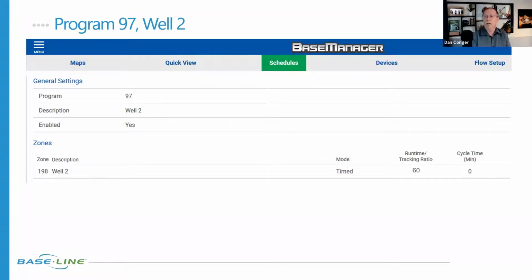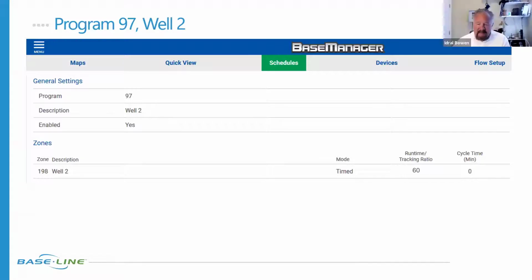And also what was available at the time. Exactly. Yeah. We didn't have that available when this system was drawn up initially, but if it was today, we would use our pressure transducer with a lake level transducer and monitor directly and take the input directly in our system. Yep.